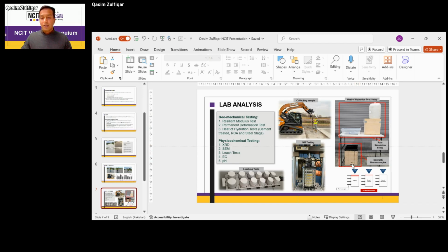We are going to have cement-related RCAs or steel slags in the box underneath, and try to provide a unidirectional supply of water in the form of this rain simulation from the top. Now, once we have the RCAs or the cement-related aggregate in this box, we are going to observe the layer-wise hydration that occurs in such aggregates to study the microstructure behavior, as well as the type of strength gain that these aggregates have in them.